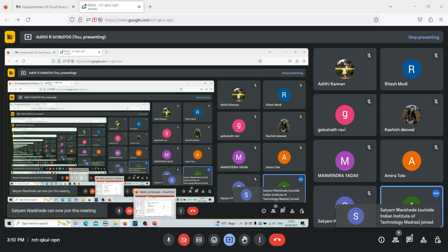Okay, so we have an equation here for strain. Epsilon at any time t, the strain at any time t, is equal to sigma naught by E naught plus sigma naught by E_R into 1 minus exponential of minus t by lambda retardation, plus sigma naught t by mu naught.